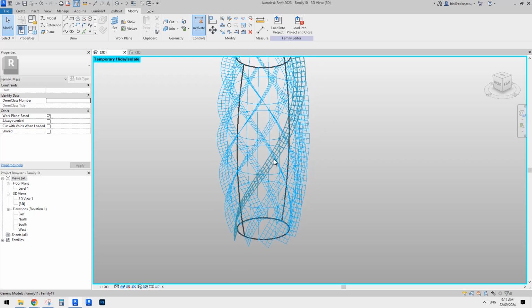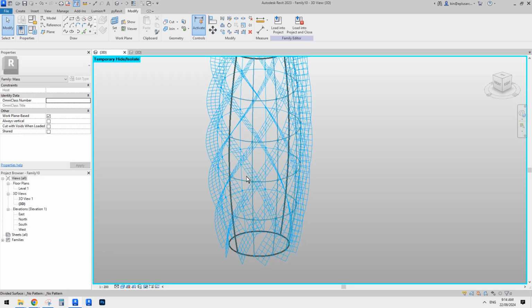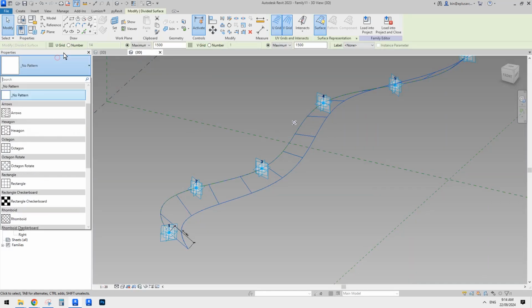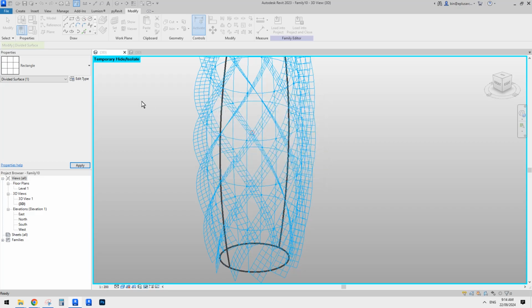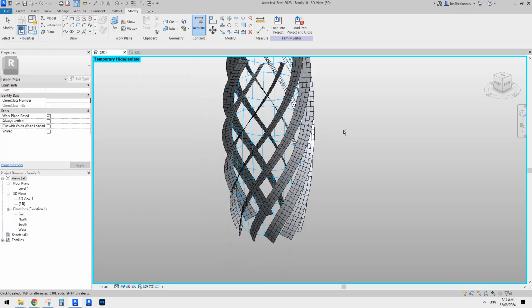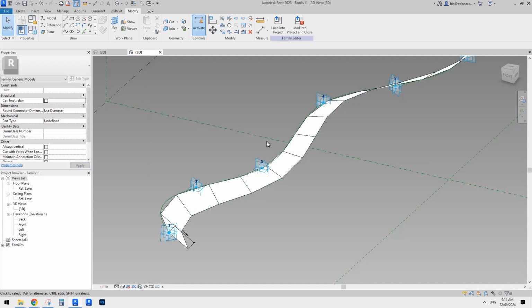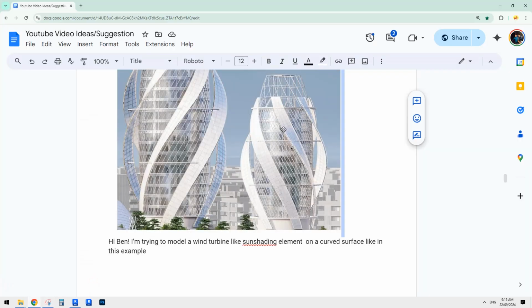and so if you load this one into a project you won't see anything, they are all invisible. What you need to do to make them visible is to apply some pattern based. So for example here, you can just choose, like for example, I'll just use a rectangle. Okay, so if I load this back, override, you will start to see some solid pieces. Okay, and then further, you can create your own pattern base. For example, you have some frame, some panels, you can start to give them materials, so it will look like this.